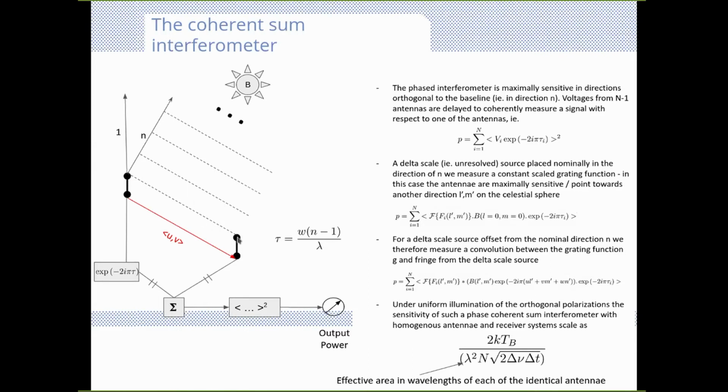So the induced voltage is going to be measured at exactly the same time on this antenna P as it would be on this antenna Q. Let's call them P and Q in this case. The antennas are separated by some distance, so there's a baseline distance here in this UV space, as we've defined them earlier on. And now, as I said, the delay tracking computer has compensated for the geometry of the problem, such that we get a signal that has equal path length between antenna P and antenna Q to the sum here.